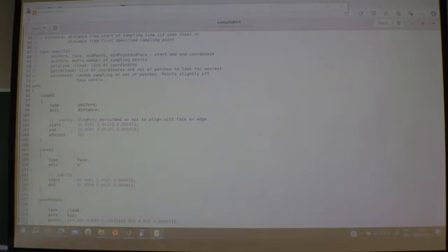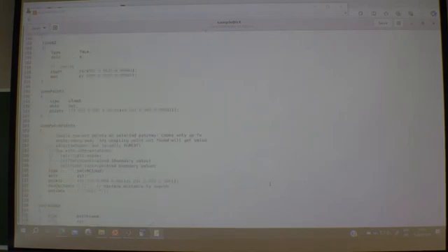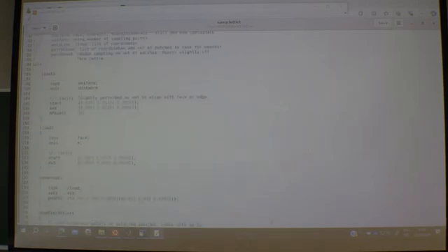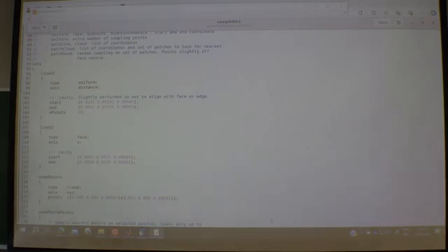And if you continue to look into this file, you're going to get a headache because you have a lot of options here. Normally, I would say you can stop already here. But I mean, you have the alternative as plot over line in ParaFoam anyway, so your choice. But here, if you look into it, you have a lot of options here. So this will be one way, say another way to do it. Just copy the sample dict file into your folder, and then when you simulate, he will automatically give you result files.